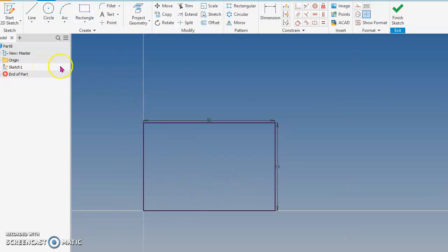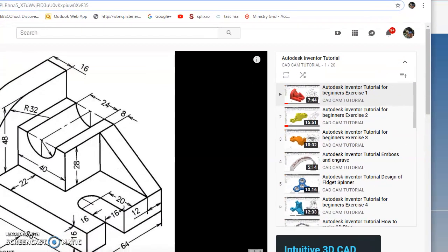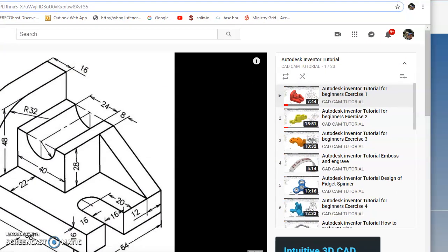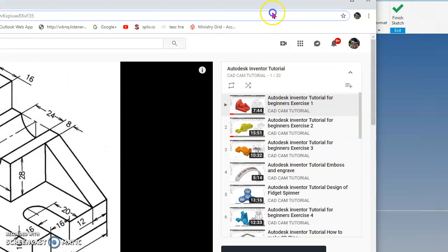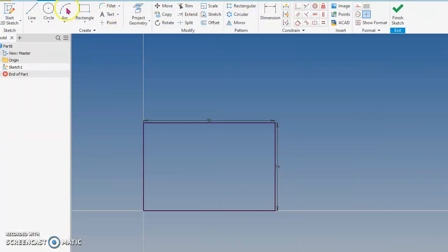Okay, I'm going to do the little slot now. That's 16 across, 16 over. So that's telling me that the diameter of my circle is going to be 16. I'm going to place a circle right here that's 16. Then go ahead and draw lines from the quadrants going out from that, just like that. It'll stay put as I add measurements to it. So you should have a 16 on here right now.